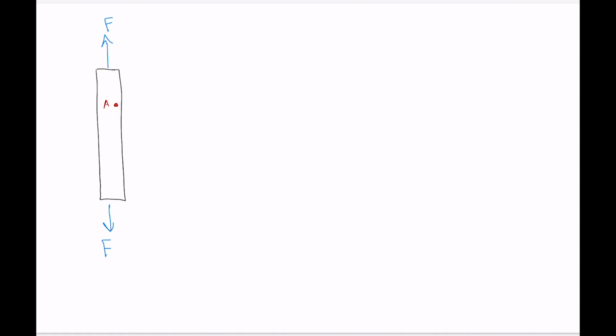What we want to do now is create, for all the different section cuts that we could possibly do, a graph that maps out the different combinations of shear stress and normal stress that we get for every section cut. So let's create this graph over here, let's do it in black. We'll put normal stress on the horizontal axis and shear stress on the vertical axis, right?